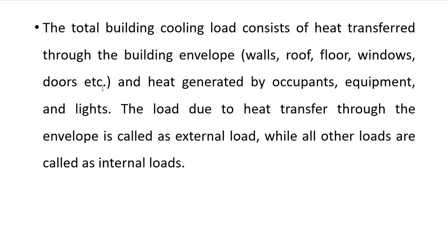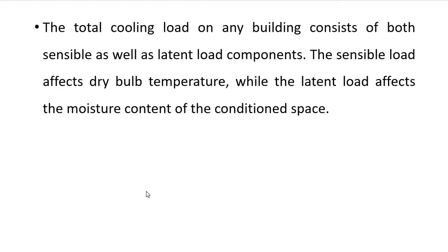And this is the heat coming from outside. And inside the building, there will be occupants, equipment, lights, machines, etc. So the total building cooling load consists of heat transferred through the building envelope and heat generated by occupants, equipment and lights. The load due to heat transfer through the envelope is called external load, while all other loads are called internal loads.